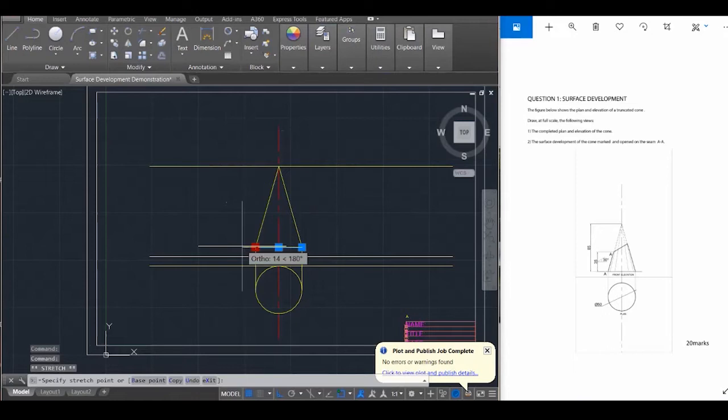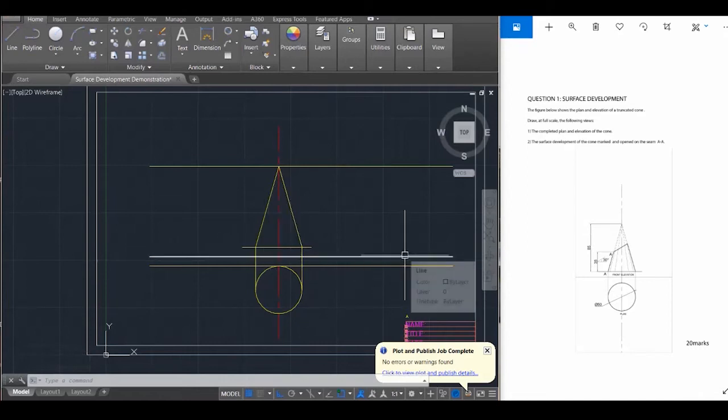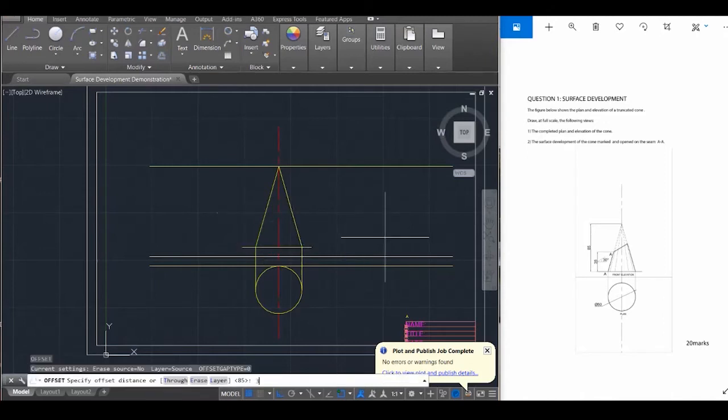Yeah, just flare that. This is just a little style there, so that the cone sits onto the ground and it's just not floating in space. Now, what are we going to do next? Now I've drawn this. Now I need to offset from my baseline 35 millimeters up so that we can start placing this cut in. So I go O to offset, that's the hotkey command O, touch the baseline, go up 35 millimeters till I reach this point.